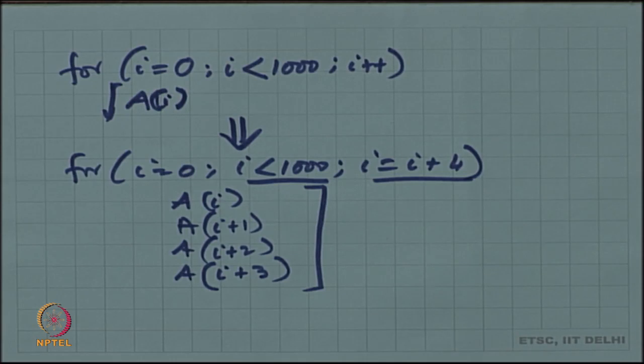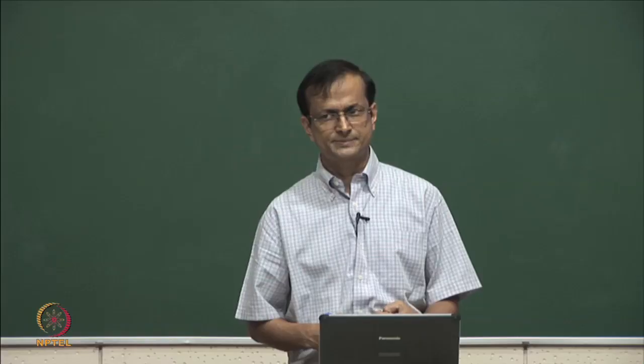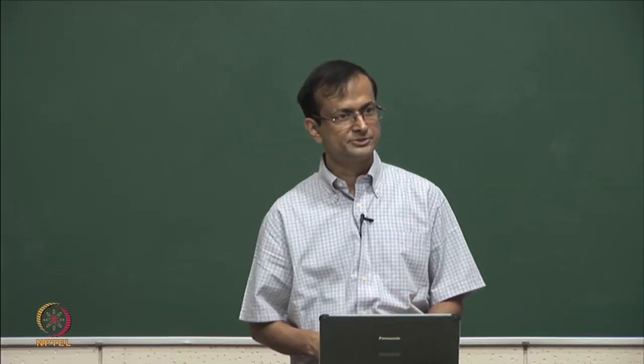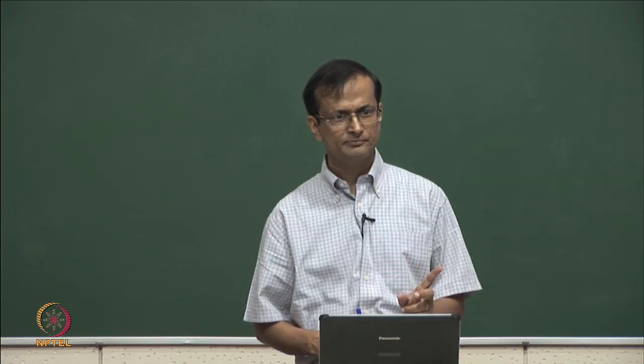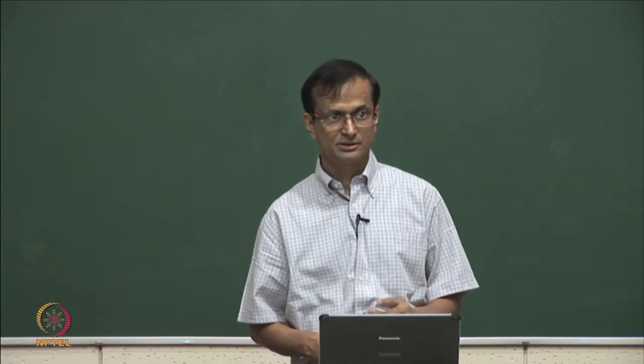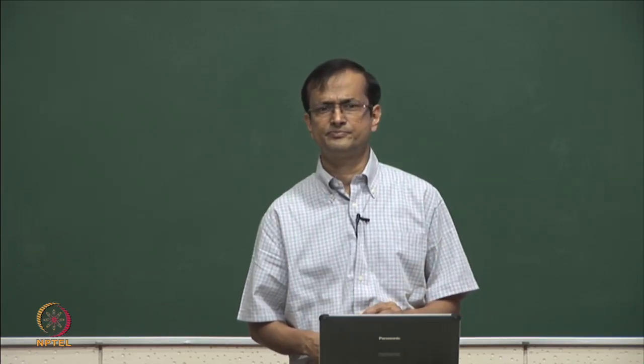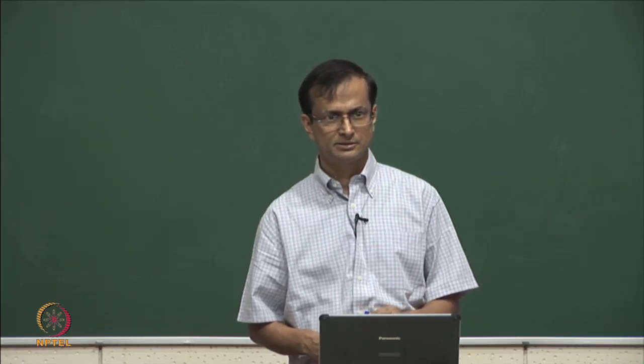So, that was the context of the compiler. In the synthesis context, there are also some very interesting trade-offs. We already saw the resource related argument, but what happens in synthesis if you expand the loop 1000 times? There is no cache, there is no instruction. Could there still be some drawback?